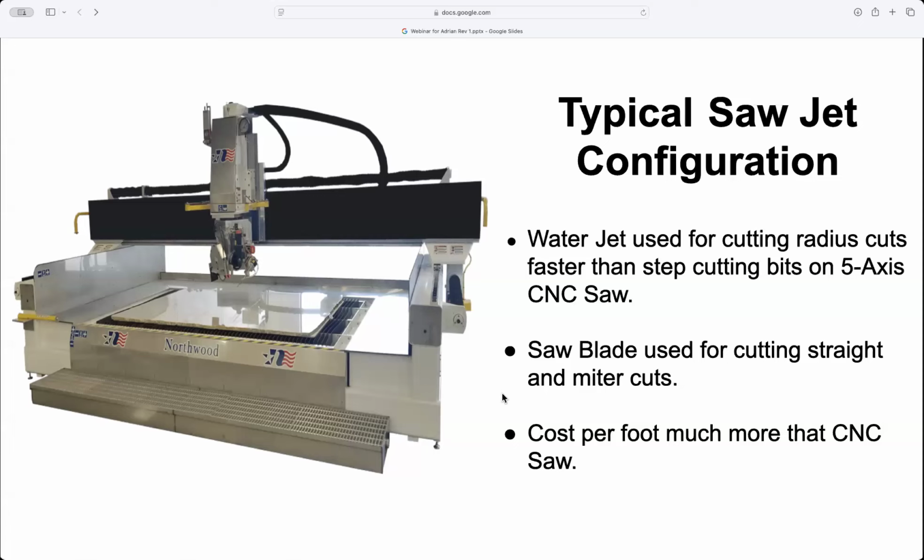Yeah, with the Sawjet configuration, there's your blade on the left side of the bridge. That table with the slats on it is where the pieces lay in, and the water shoots into that table, and that stops it from cutting any further because it hits the water. That's what fills up with mud and muck, and they have to pull those slats out and dig it out. This is a compressed picture, so it's much larger than it looks here.